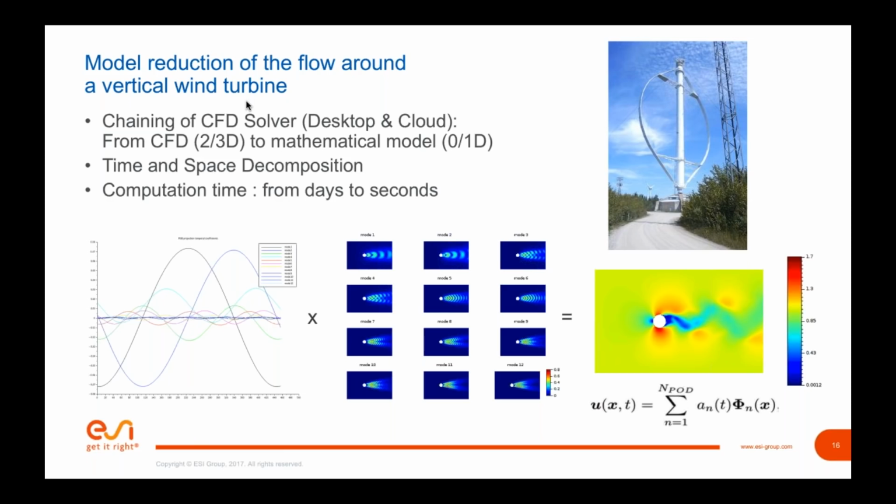So what we came up with is a reduced order model built from one of those turbines, which we used as an input for the complete field simulation. From a mathematical point of view, it's a decomposition of time and space. Starting from the complete, difficult Navier-Stokes equation, it splits the time component from the space modes. And this is what performs the reduction. So you just cut, like an FFT, to the first modes, and you can capture most of the information at a much lower computational cost.